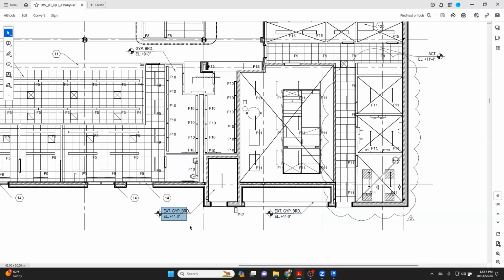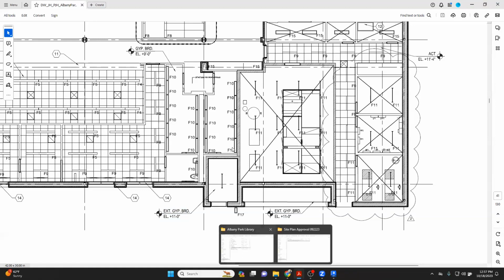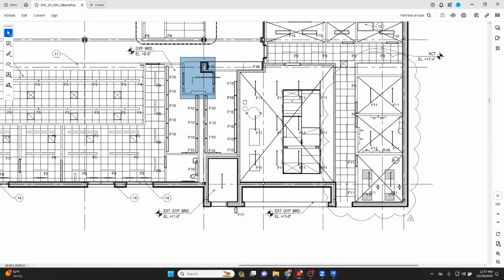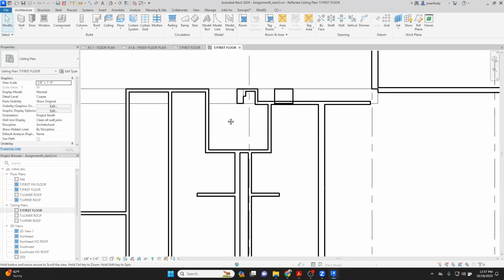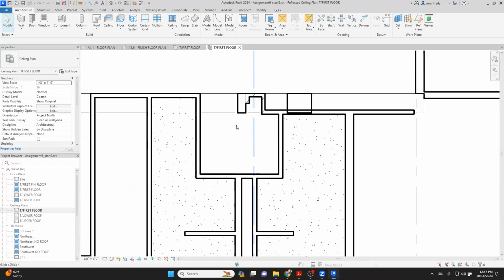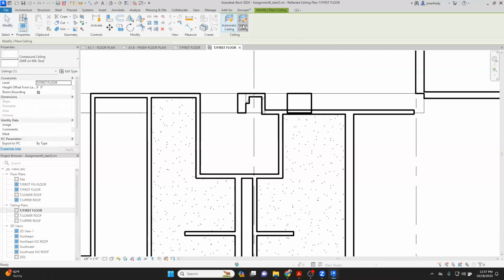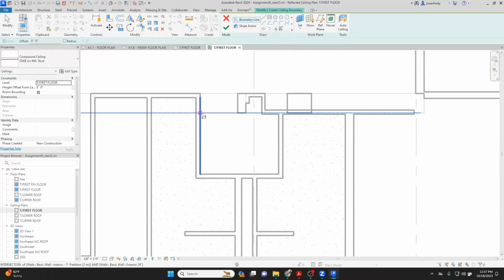Okay. And so that's what we're going to do for the interiors, and we're going to use the little area here for gypboard, don't forget. So if it doesn't have an X through it, it's going to get gypboard. Just assume if you see a white area in the ceiling, there's a gypboard ceiling in that area. So for example, here, if I try to do automatic, it's going to escape because there's a big hole right here. I can walk through that opening. So I want to do a ceiling that's drafted. I sketch it. I just draw a rectangle in there and just be done with it.